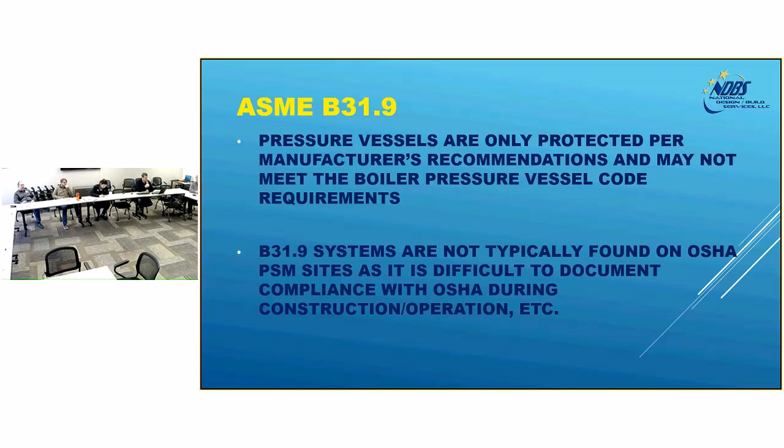Now, say you're doing a small manufacturing facility where there's one hazardous room, and they got drums in that room. The room itself is considered to comply with the building code, so it has to have blowout walls, it has to have special exhaust and all that. But they may or may not have enough of that one chemical to classify them under the OSHA.